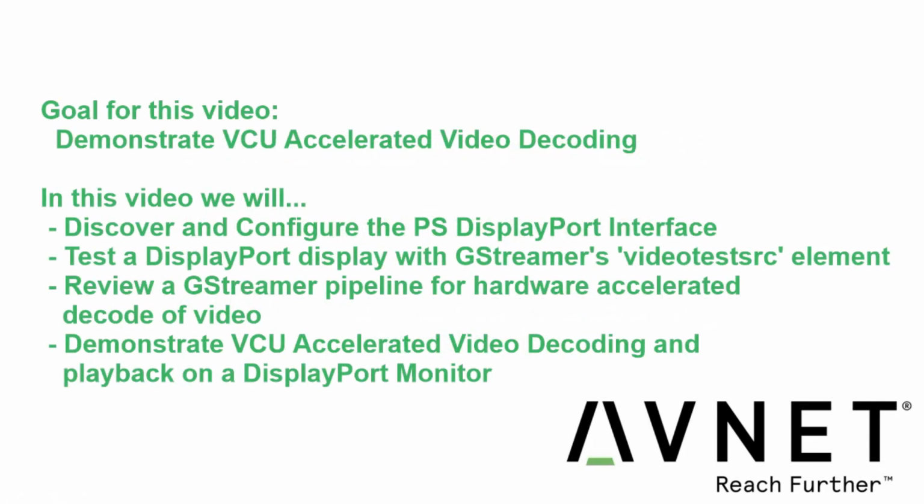This provides a great starting point to explore customizing your PL for your development effort. In this video, we're going to demonstrate an example GStreamer pipeline for VCU accelerated video decode and playback. We're going to cover how to discover and configure that DisplayPort interface from the command line. We're going to test the DisplayPort display with GStreamer's video test source element. We're going to review a pre-constructed GStreamer pipeline for hardware accelerated decode of a local video file, and we're going to demonstrate that decoding on a local DisplayPort monitor.